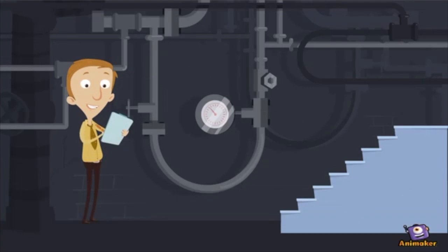An electricity plant equipped with pre- or post-combustion carbon capture technology will require between 10 to 40% more energy than one without it. This is energy needed to run the equipment to remove the CO2. Accounting for this increase means that the net amount of CO2 captured is approximately 80 to 90%. Alternatively, an oxy fuel system is able to capture almost 100% of the CO2, but the additional systems for removing nitrogen and sulfur lowers this value to roughly 90%.